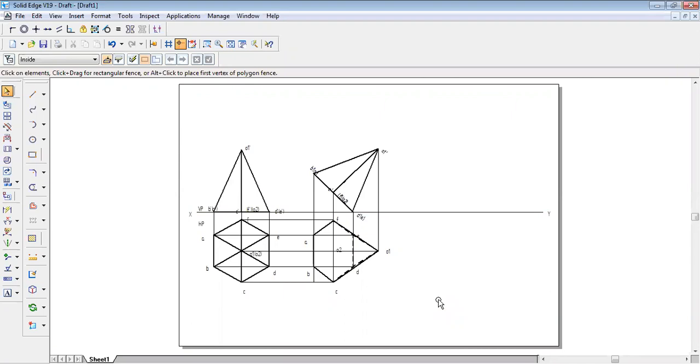Whether I have to draw a locus or not depends on the question, for which I need to go back and read the question, looking for the words "appears to be." If I have the axis appears to be at VP at 30 degrees, I'm not going to use the locus method. Here, when I go back and read the question, I don't have any "appears to be" word, it is only VP at 30 degrees. That means it is a locus problem.